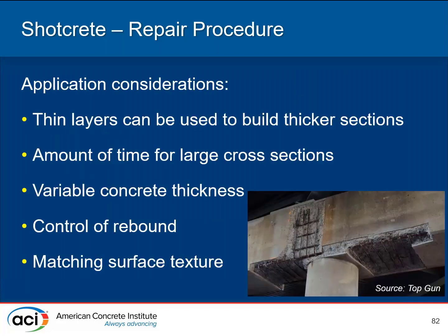These are some of the things that you need to consider when you're thinking about rebar, whether shotcrete's appropriate, how you're going to be building up some of your thicker sections. You may need to do it in multiple layers. It can be time consuming for large areas. The volume you're applying at once is limited to the size of your hose. You can't dump a big pile of concrete the same way as when you're forming and pouring. Control of rebound comes into play, and it does still need to be finished.